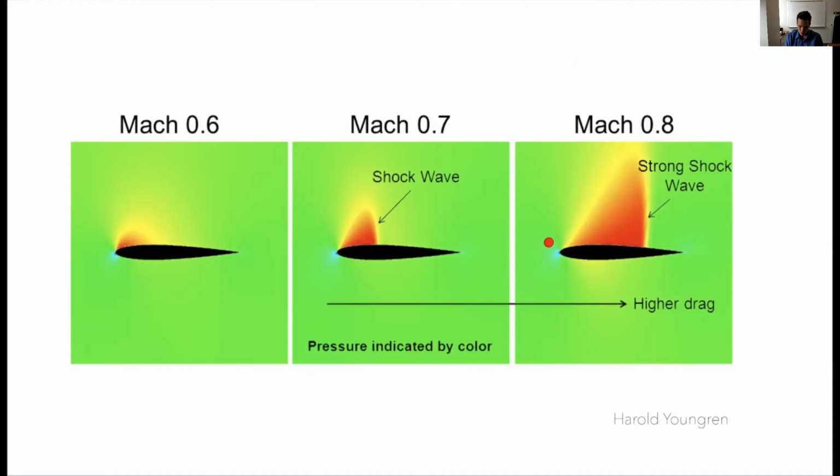As you speed up over the airfoil, you're going to have regions of supersonic flow that potentially terminate in a strong shock wave. Now, we want to design the wing and the aircraft so that these shock waves are weak. There's a region where a relatively weak shock wave doesn't have large entropy increases. It's relatively flat, and then it starts to increase quite dramatically in terms of entropy increase and drag increase.